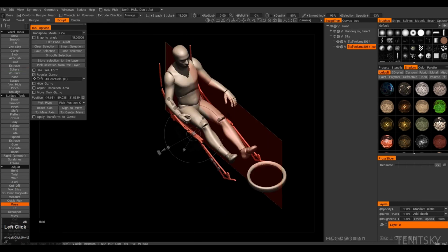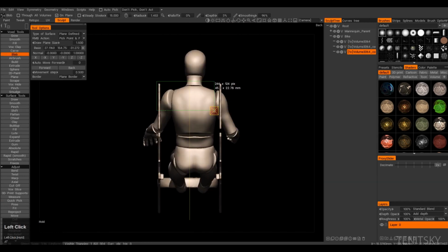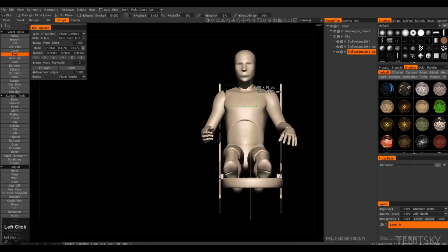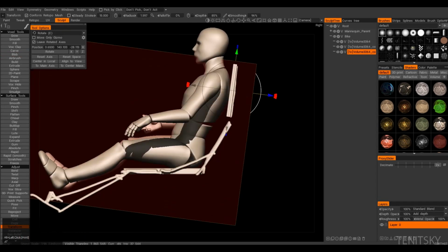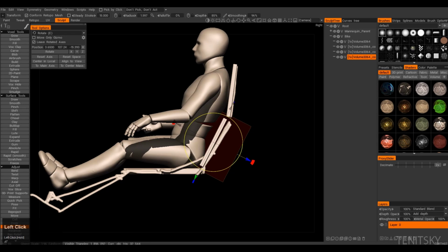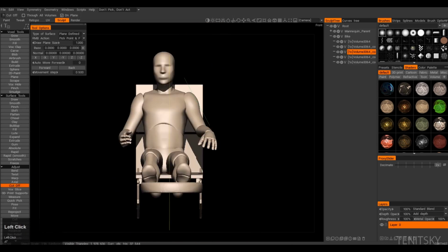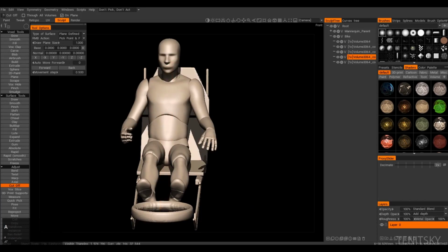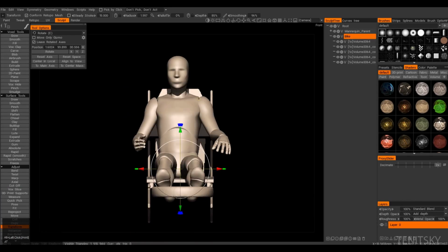And I'm using on plane on and off all the time. So on plane actually right now is on a hotkey. So every time I want to draw in a certain plane, I switch to the hotkey and then start to draw.